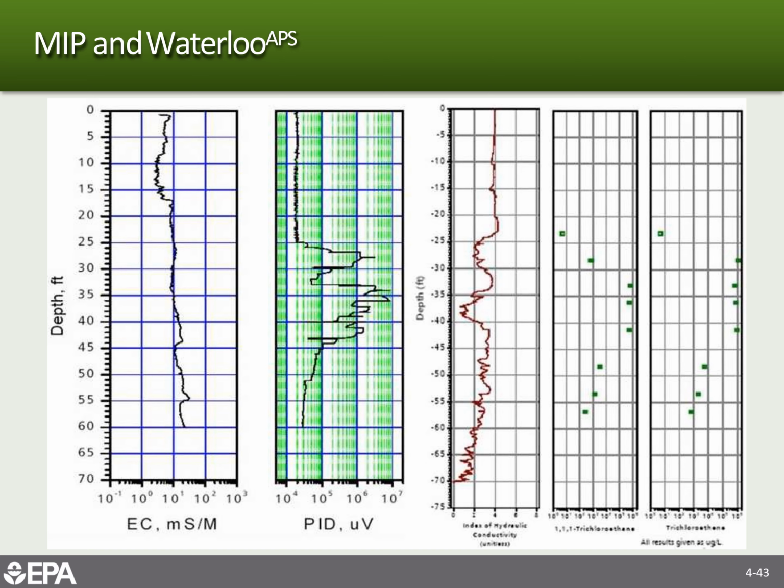You see they're pretty high in this higher conductivity zone, and still pretty high in this lower conductivity zone. But then there's less of it as you go further down the hole, and as the formation probably fines into a finer grain, a fining downward sequence. This is an example of using these multiple tools to give you foot by foot or better resolution for your contaminant distribution.